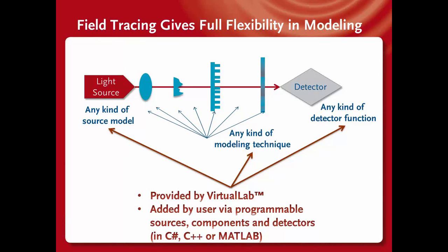So you can program sources, components, and detectors, and you can do this in C#, C++, or MATLAB. The only restriction you have is that as an input field, for example for your component, you need an electromagnetic field. And as an output, again, you have to give back an electromagnetic field. And in between, you can do whatever you like.